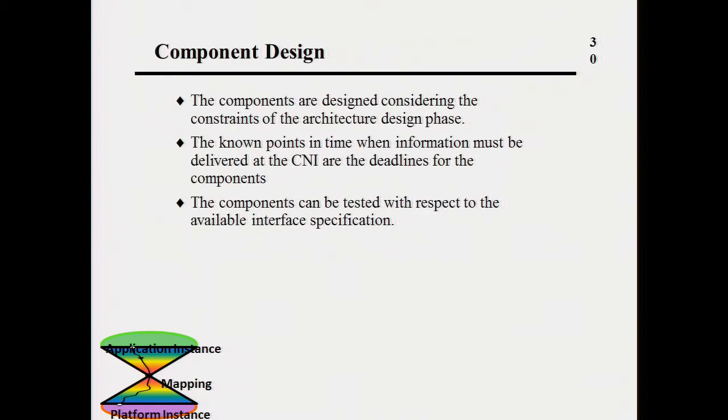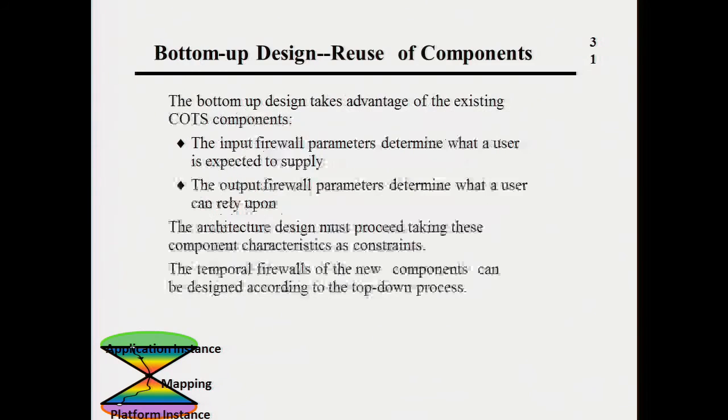Right? Now, when you design a microprocessor, this is exactly what you do. So you have a clock, then you try to do the combinational logic in such a way that the propagation time is within that clock. If the propagation time of a signal between registers is longer than that, you have to go back and readjust the clock, okay, because it takes longer. Right? And this is exactly the same kind of mechanism here.